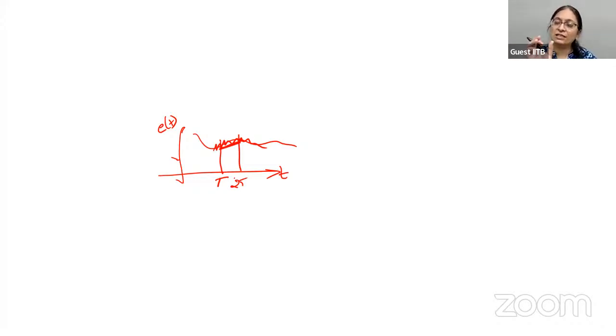So this outcome I have mentioned in the lectures, saying that the derivative needs to be always associated with a low pass filter. Now, the low pass filter appearing in series or in parallel makes a difference. So just go back and analyze it based on that. The reason is the derivative, which is always notorious, right?